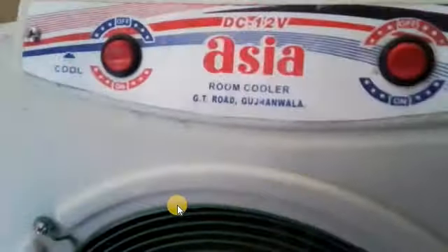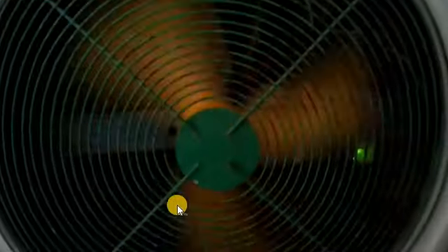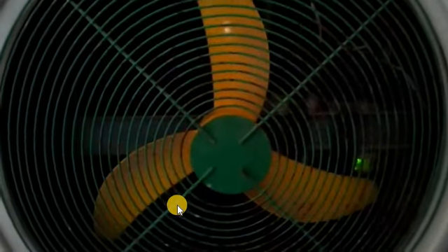Now it is at very low speed. Duty cycle is about 2 to 3%. This way we can change the speed. Again push this push button, it becomes off. Push this one, now it will become 0 duty cycle, 0% duty cycle. Again the cycle will start. Again it will be at high speed, about 100% duty cycle.